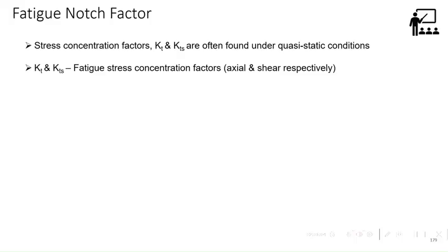When there is a situation where something has to be mitigated, as usual one way is to redesign where there may be an issue. You see whether there is any way you can clear it. In that case, you can come to the practicality of the fatigue stress concentration factor. You can use that, which is less than K_t.